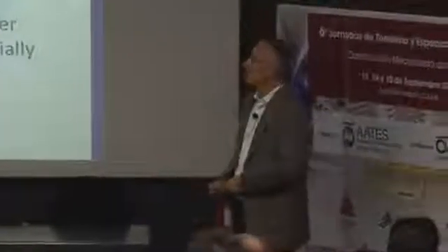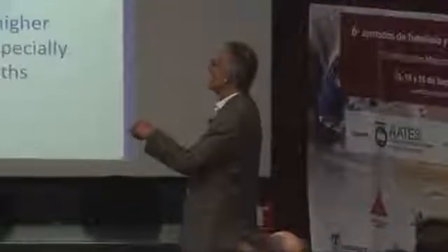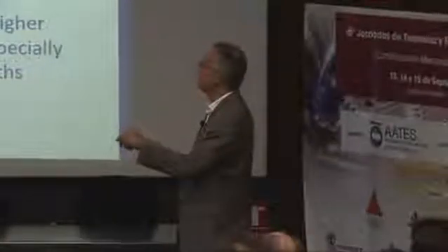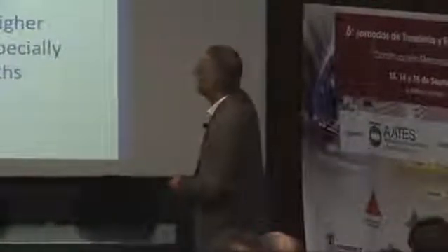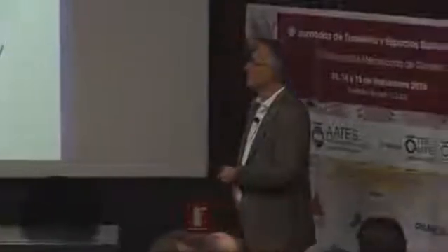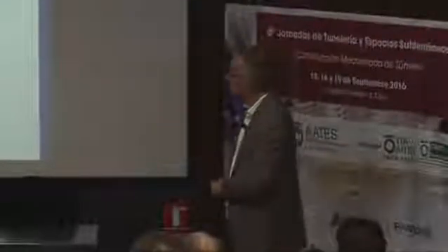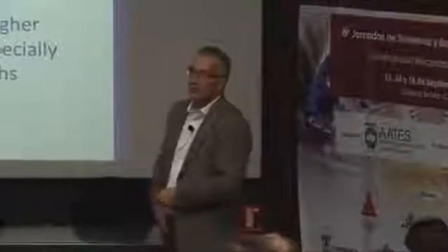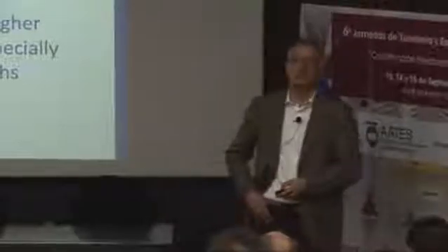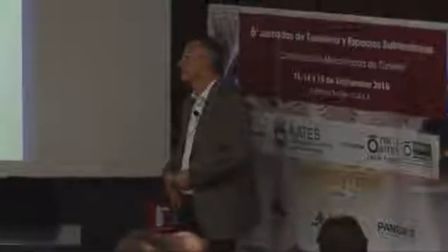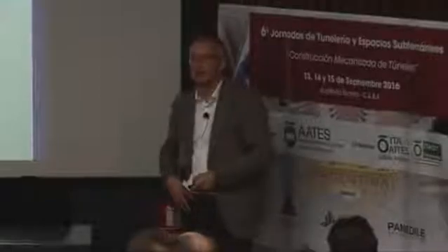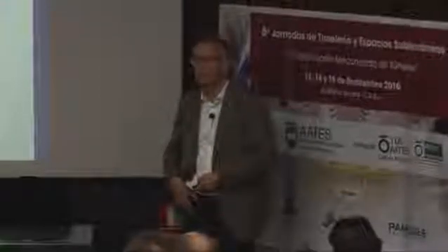With the introduction of 3D modeling, we then had the first 3D models with an arching effect in the horizontal plane. That was used quite a lot in diaphragm walls, and it was transferred into tunneling. You see here the tunnel face, and then you have your arching model right on top. But it goes all the way up to the surface as well, and thus, especially in deep tunnels, it still creates quite high values for your face support.